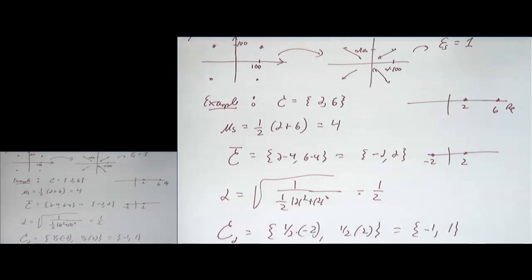So this is just a way of ensuring there's no DC. There are different transceiver structures that give you DC offset, which has all these problems with DC components. So it's actually there to make sure the analog signal has some properties. Most communication signals are zero mean, or they might even explicitly make the DC component disappear. And we'll see how they do that in OFDM signals.